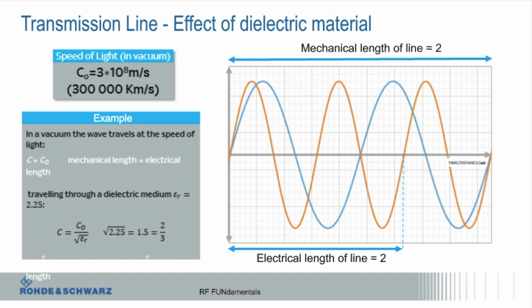If you say, and I get this all the time, so if you get a bad cable and you say, okay, I want to measure all my S parameters of my device with a bad cable, and then I look at a good cable, after you've done the calibration and you look at where is my residual S11 of my cable at the calibration point, you might find with a bad cable, and I've seen this, it might be 20 dB, right? That's as good as it's ever going to get.